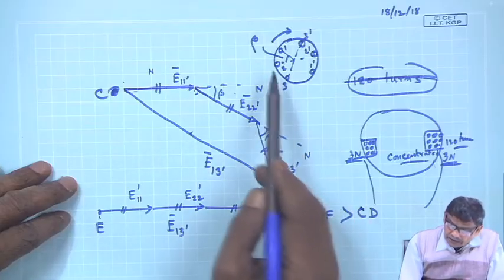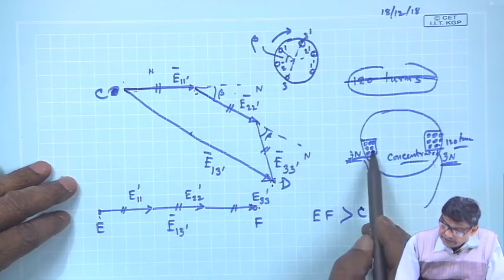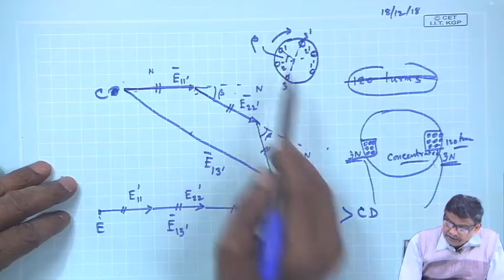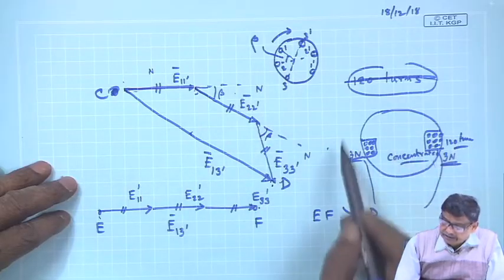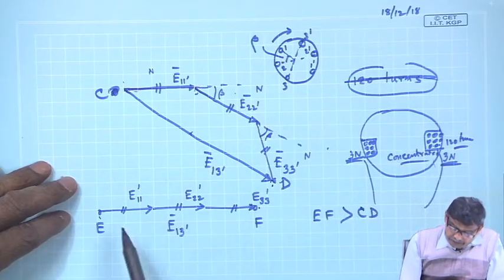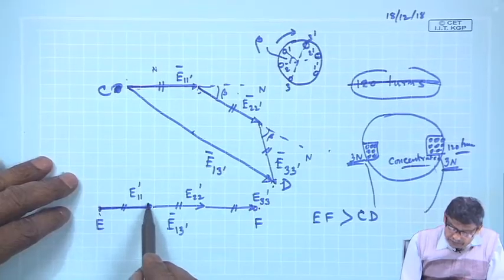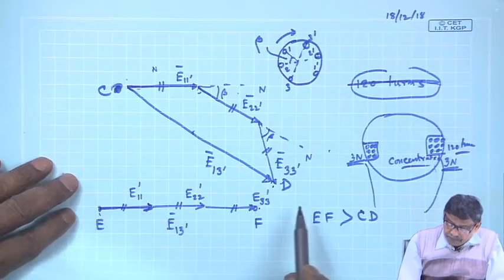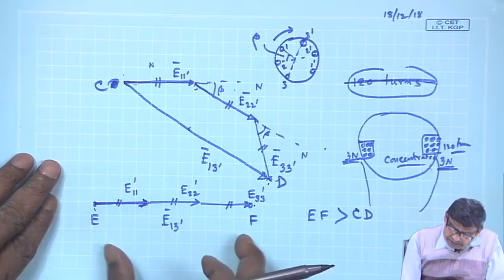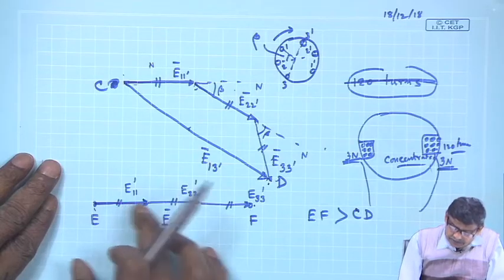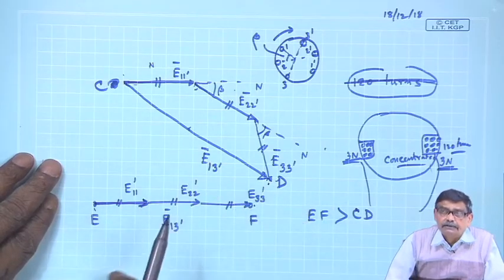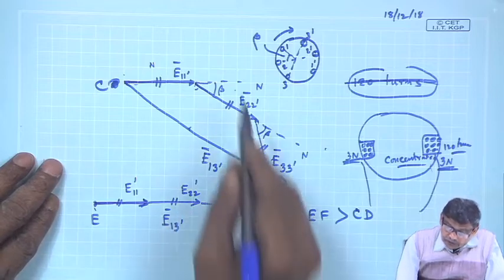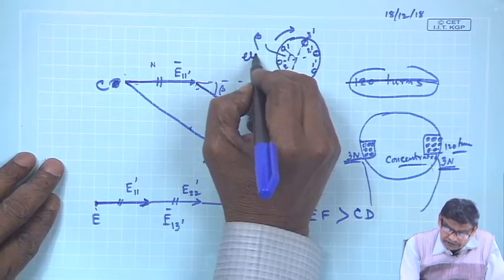And you now imagine all the coils are concentrated in these 2 slots. So, that 3 n turns are there here. Then these voltages would have been cophasal, and this length will be just 3 times these voltages, and you will get this one. So, this beta, all the angles will be electrical.